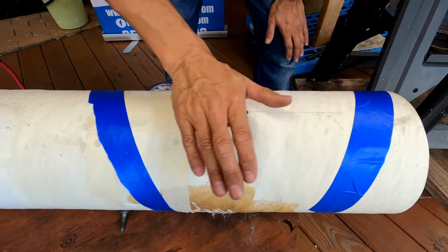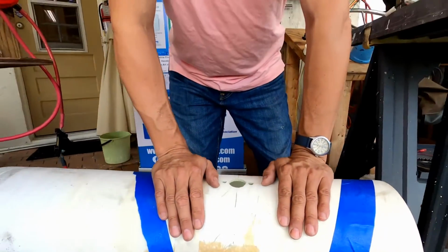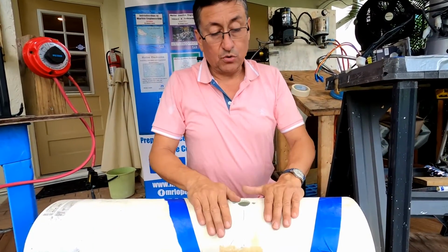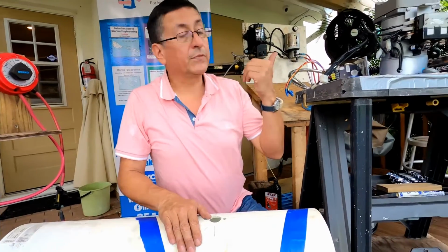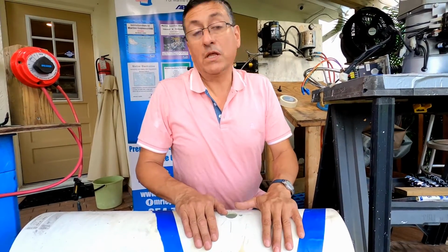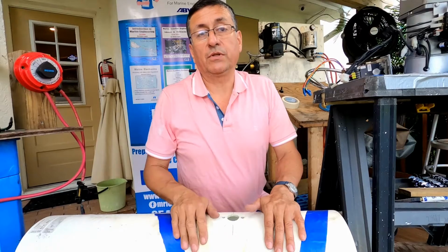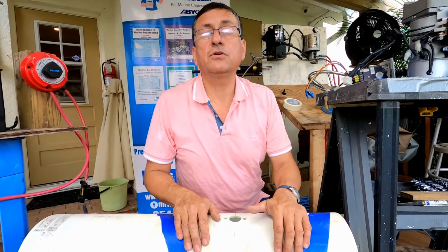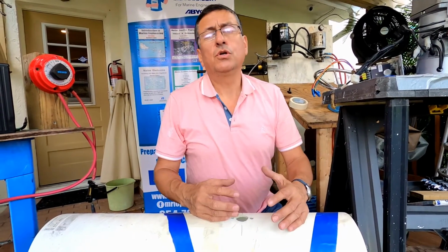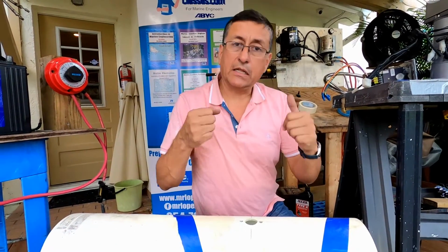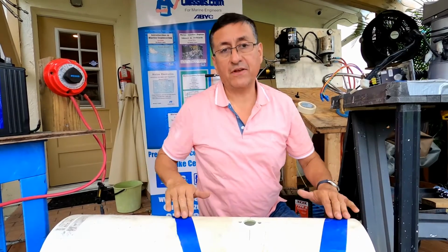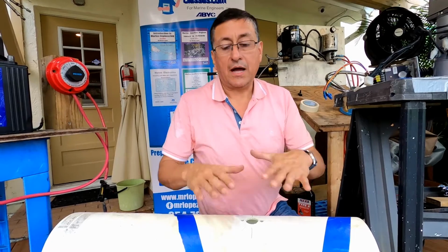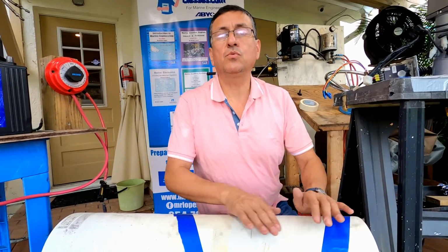This is the tunnel. The tunnel is specially fabricated in fiberglass. Those tunnels come with the bow thruster unit, according to the recommendation of the manufacturer. And in the previous explanation, I explained the procedure to make the hole on the boat, to install the tunnel, to laminate the tunnel with fiberglass, inside and outside, and to paint. After that, the system is ready to install the tunnel.